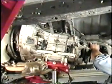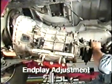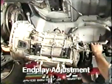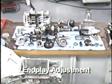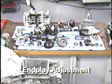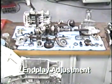As an example of another typical transmission adjustment, let's look at end play adjustments, this time using an M50D. Assume you've replaced the output shaft tapered roller bearing. Anytime a major component is replaced that affects the length of the subassembly, you must measure and possibly adjust the end play.